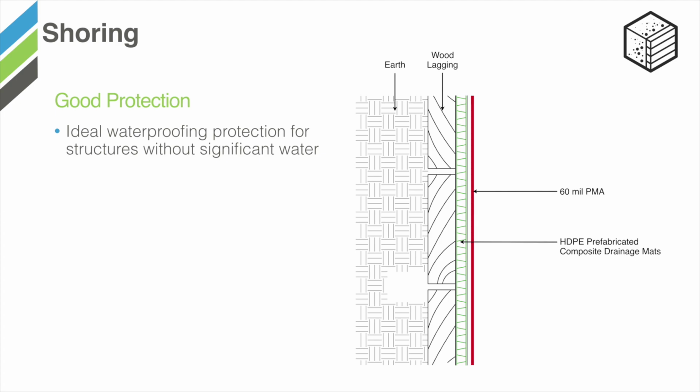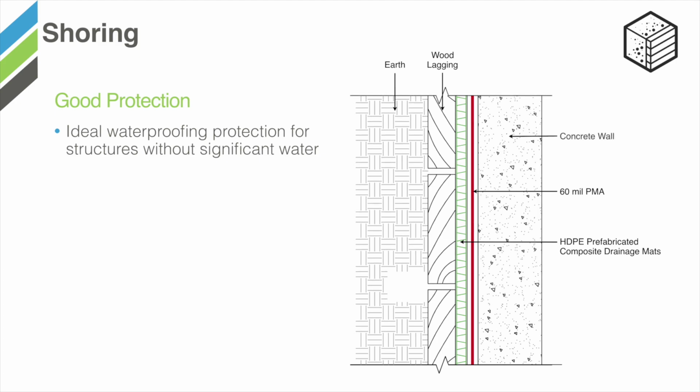In this unique situation, the concrete is then cast up against the waterproofing membrane, or instead of concrete being cast, it can be shotcreted up against the membrane system. What happens is the membrane or the waterproofing system becomes fully integrated with the below-grade foundation wall.